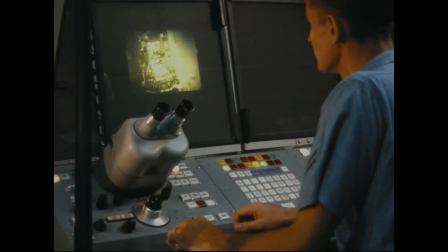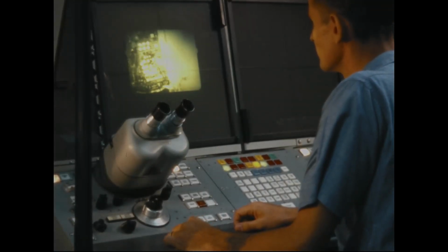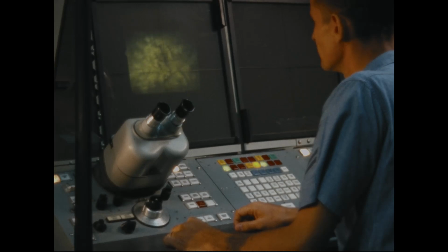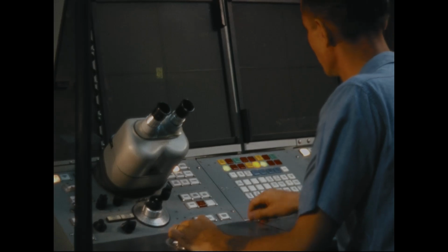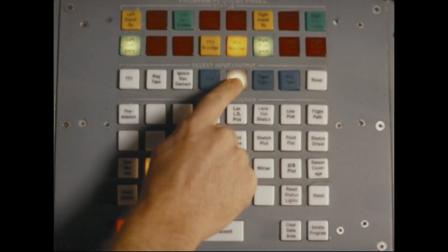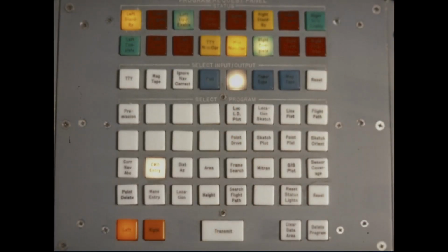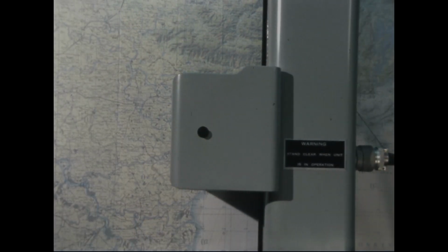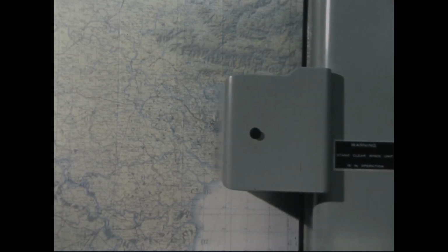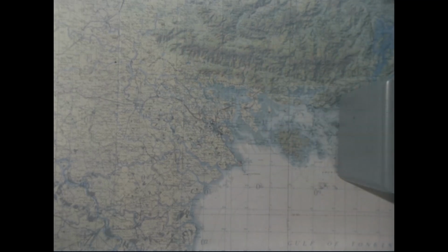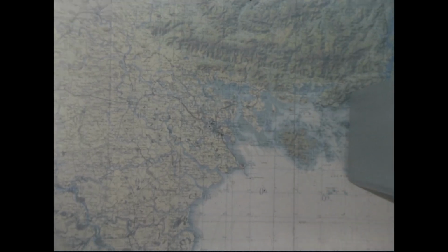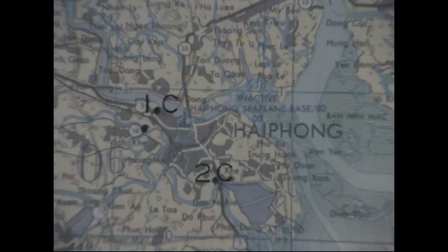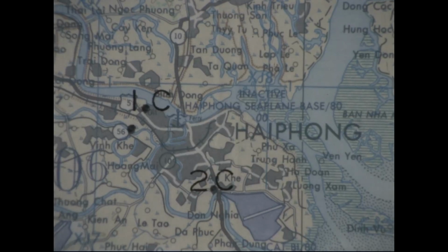As each of these familiar points with precisely known geographic coordinates is now located on the viewer, the code matrix data for the frame of photography containing it is entered into the computer via the code matrix data entry program. By means of programs that are explained later, a plot of these points, based on the code matrix block data, is made for correlating with the checkpoints already accurately plotted. This is the error.